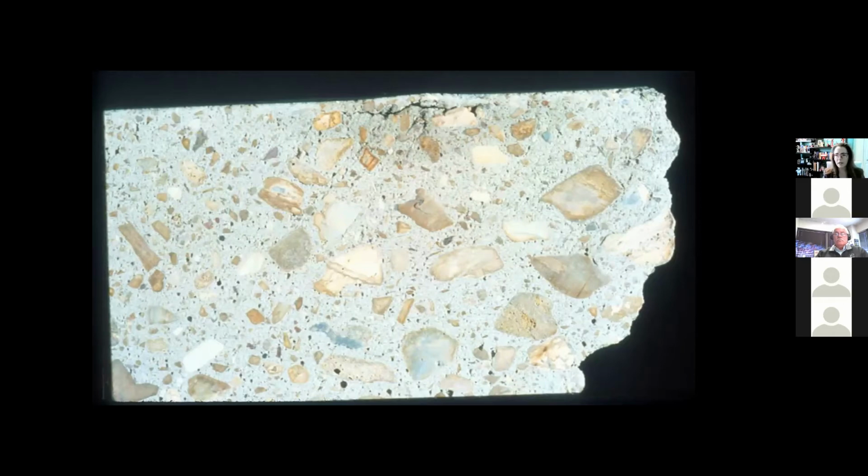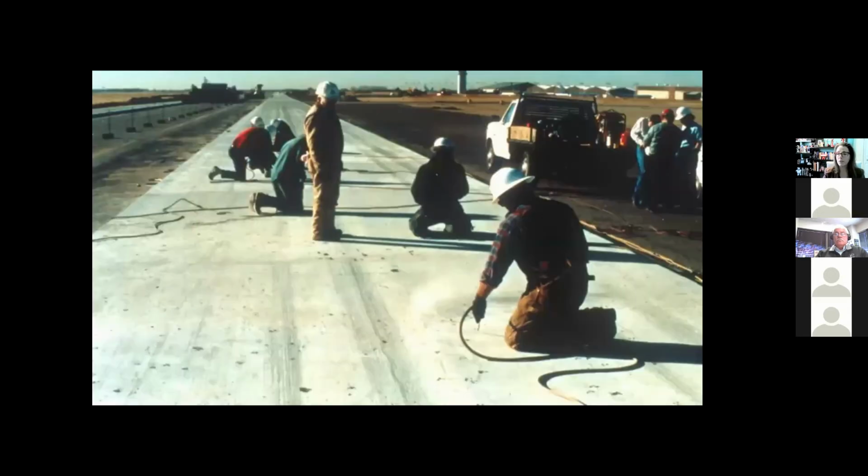Is this a problem for you? A couple blisters on the surface of your concrete? You should know the answer by now. It depends. It depends on what your surface quality needs are. Truly, this is a blemish for most structures. However, if you need surface ride and abrasion resistance, then it is an issue. And one example would be the project shown here. This is an airfield where they had severe blistering on a runway.